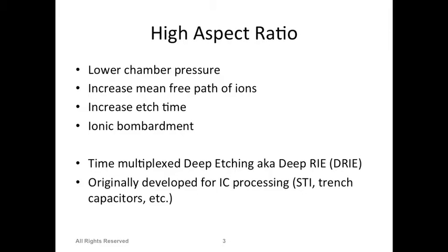Because if I use a regular reactive etching, the process is fine. You can start etching at maybe 50 nanometers per minute. You can go on and on for a long period of time, but then you start also seeing polymer deposition, and that creates a problem, because then you cannot really etch deep inside the silicon.